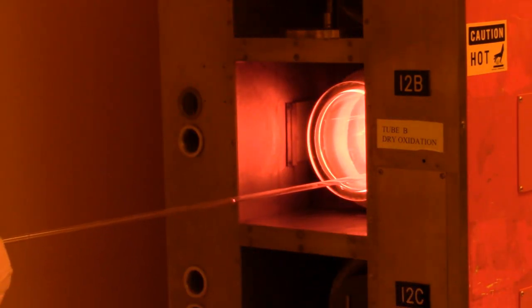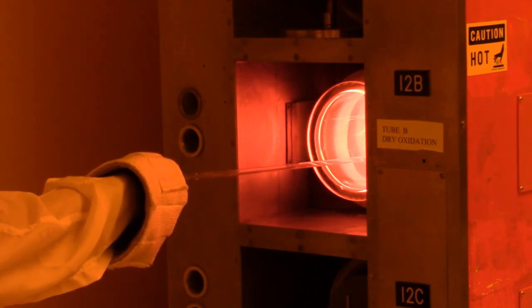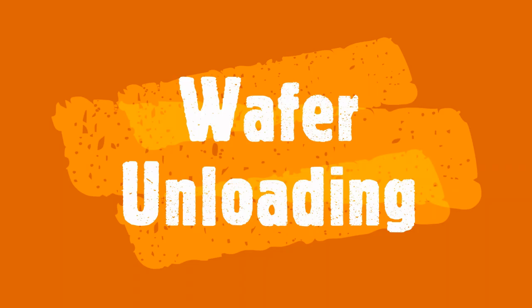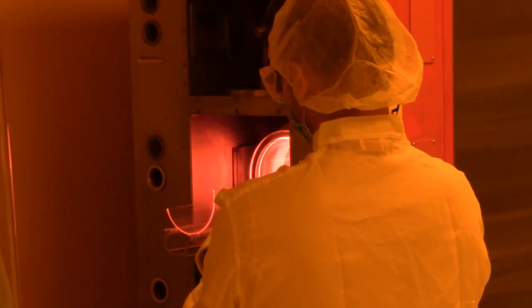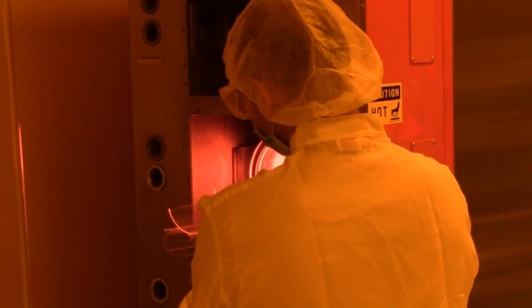Okay, so now the wafer is pushed to the halfway point, where the oxidation is actually supposed to happen. Now that it's been 20 minutes, we have switched off the oxygen supply, and we're going to take out our wafers.